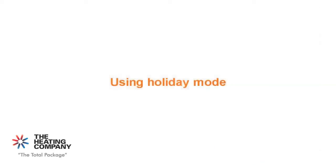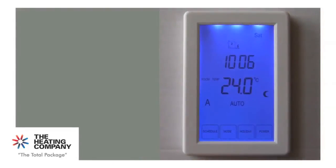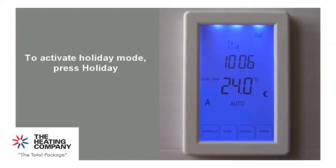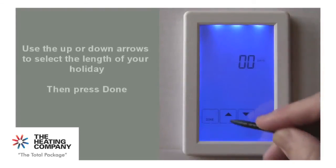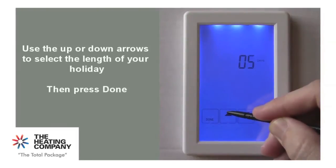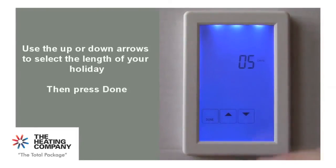Using Holiday Mode. Holiday mode means the unit will turn off for up to 99 days, only turning on if the temperature falls low enough to activate frost protection if you have frost protection turned on. To put the unit in holiday mode, press the Holiday button, select the number of days you'll be away, in this case 5, and press Done.